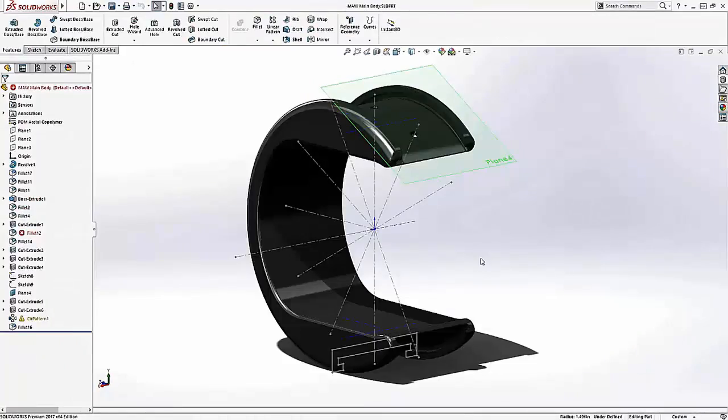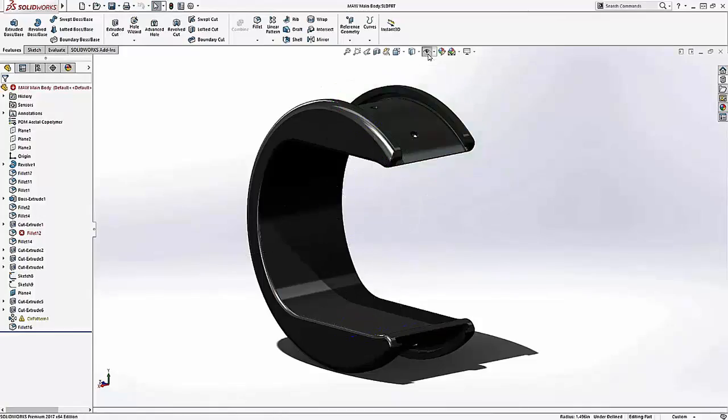Now one of the things you've probably found yourself while working away in SOLIDWORKS is that parts and assemblies can contain many different item types. What I mean by that is planes, reference sketches, maybe axes, and so on. Now in 2017, to make the display instantly clutter-free when you don't need to be seeing all this, you can simply click the button and hide everything out, or you can show the previous visibility state. Now it's really powerful to be able to do that with a single button click, because previously you would have had to go in and turn them on or off individually, which could be a little bit long-winded if you had a lot of items shown in the graphics area.